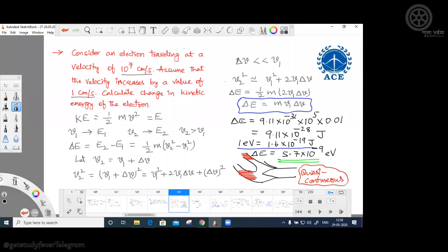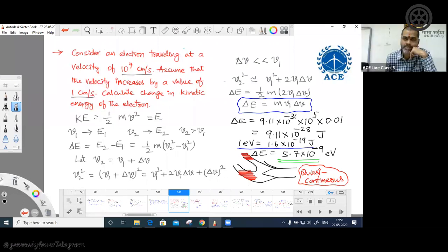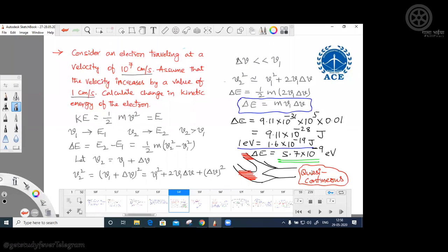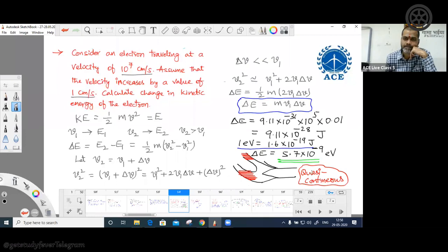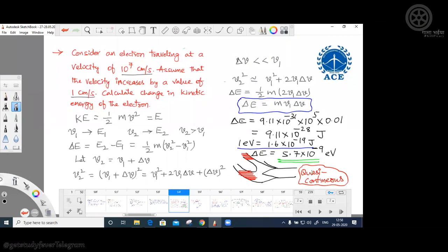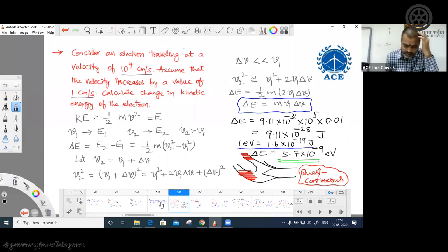Yes, sir. Sir, NC we have drawn as density, number of states in conduction band, but when we are coming to the concentration of electrons or intrinsic concentration, we are considering only that part of NC which is coming under that Fermi-Dirac graph, no sir. See, one second. If you see the equation that we have given for n, how you calculate it, you are integrating, no? Suppose you take the concentration of electrons, n equal to integral EC to ET, n of E dE into f of E comma T.